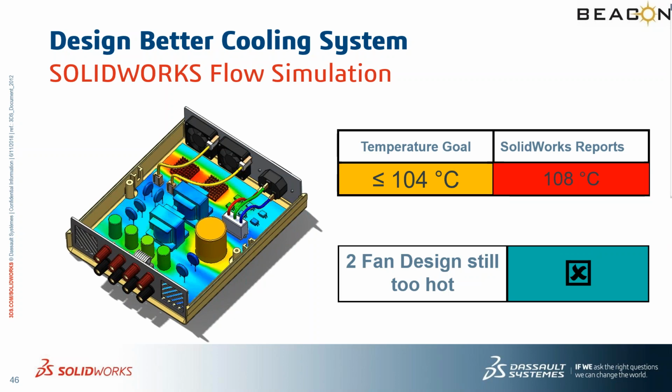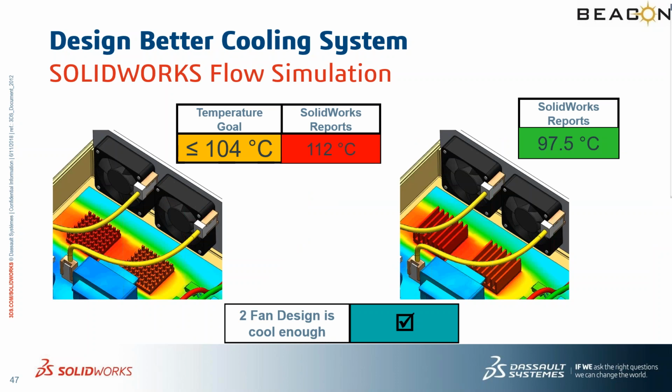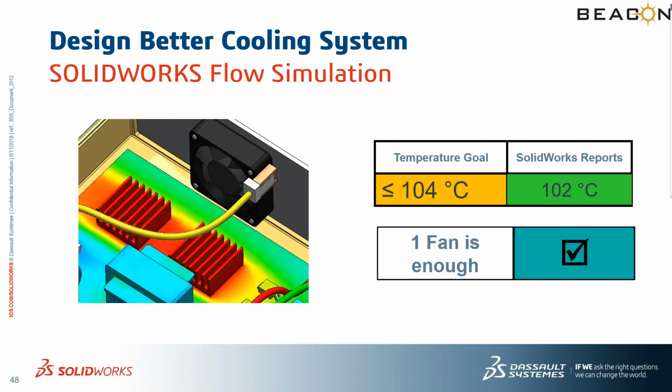In this particular example, I then went for a change in the heat sink, then applied two different fans. Then it definitely shows a temperature way less than what I wanted. It is close to 97.5 degrees centigrade. So that means it is much lower. Of course, it is good for me, but I wanted to look at whether one fan would be sufficient or not. So I've tried with another fan location.